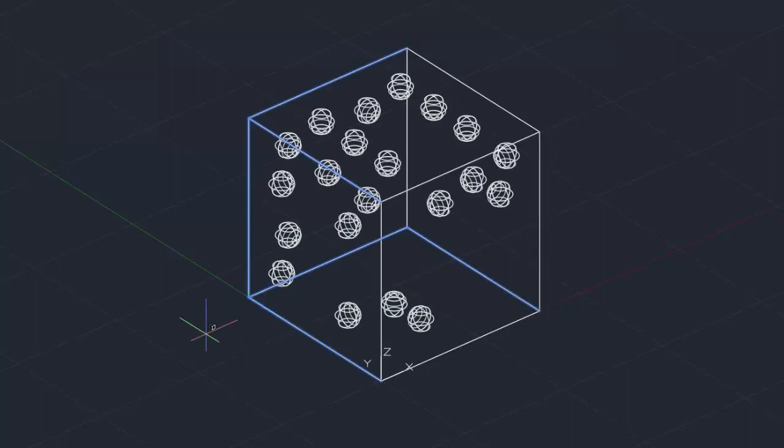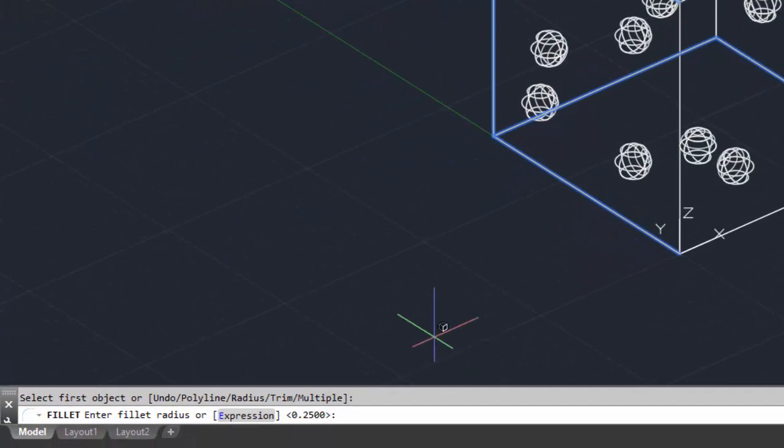Once we've clicked the object and we've accepted the 0.25 radius, so we just hit enter, you'll then come up with a command which is loop, which will take a plane of any joining lines. In other words, it will just take the 4 edges around there if I want to do just a straight loop. Or C enter, which I've just entered, for a chain.